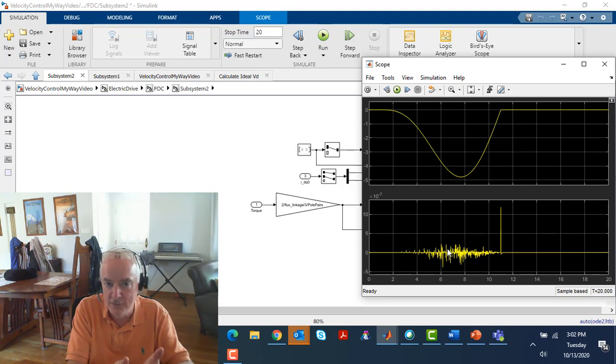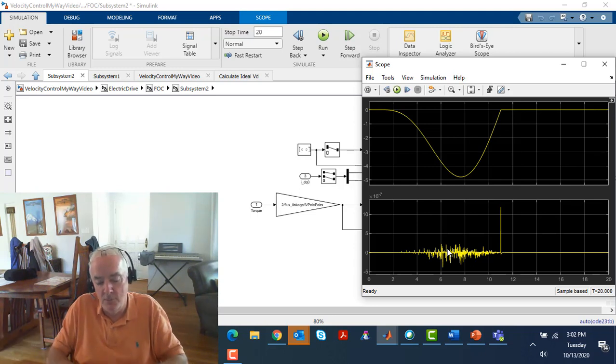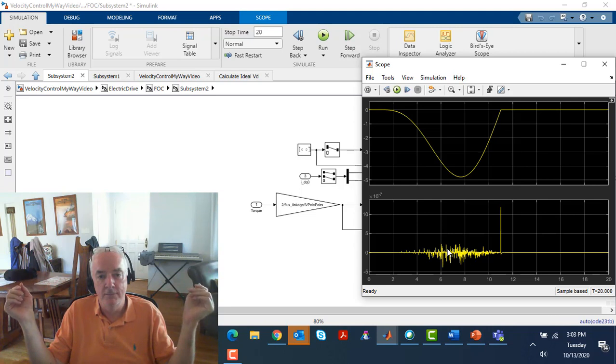And so our presumption is so strong, it's part of our calculation of what the voltage is for, well, D and Q, or it's calculated here, but ultimately gets reconverted back into the A, B, and C space of voltages that we're going to put on those terminals, right? And if we're wrong, the calculation is completely wrong, right?